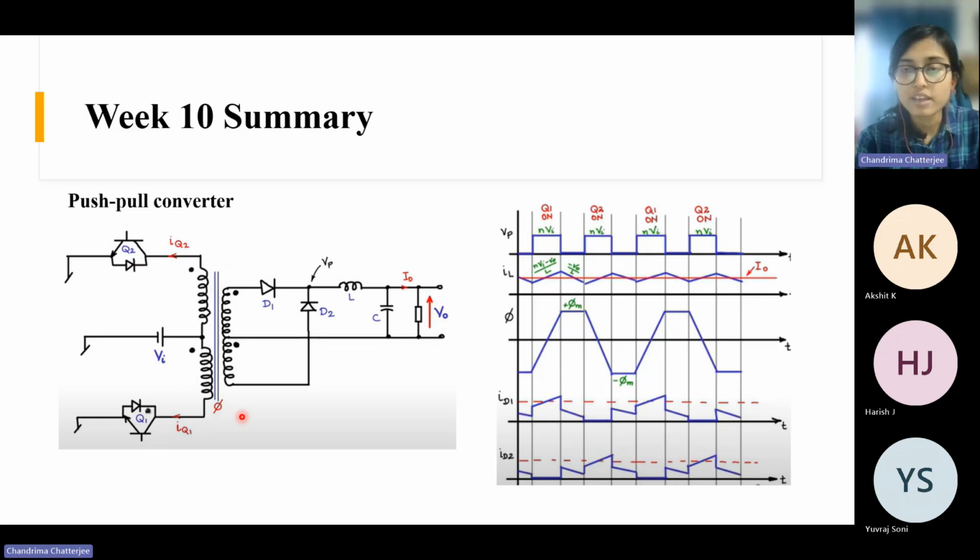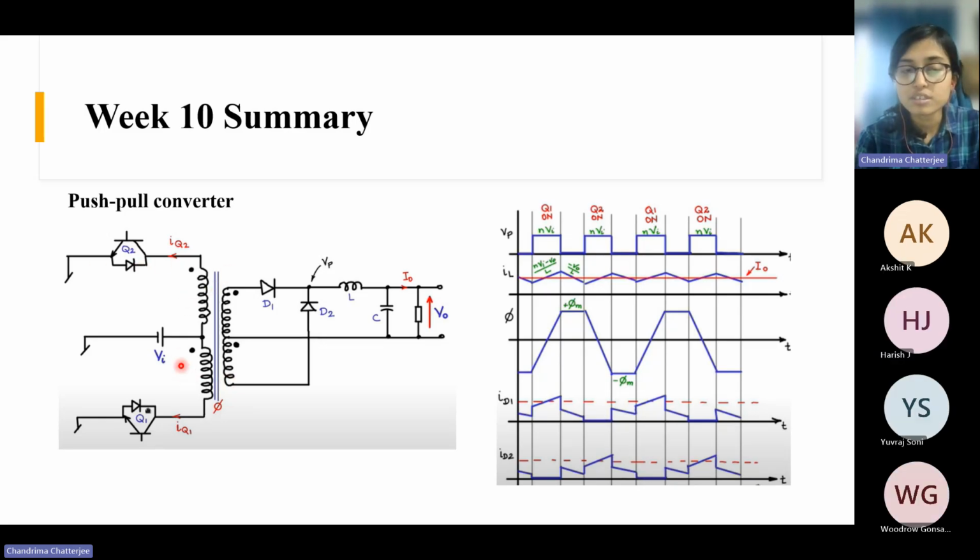But as these windings are coupled, if Vi voltage is getting induced here, then the same voltage Vi will be induced here if these are 1:1 windings, and here also you will get some induced voltage based on the turns ratio, right?